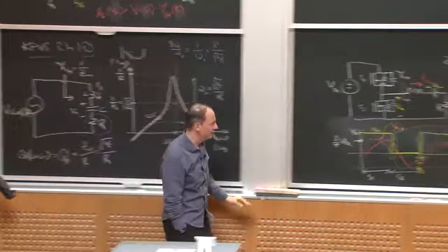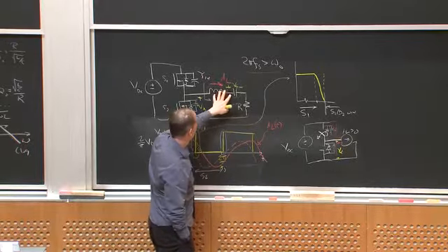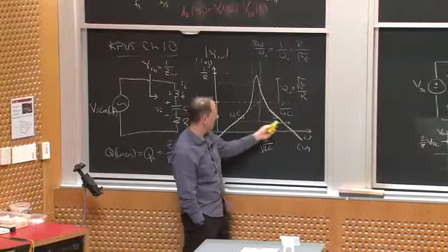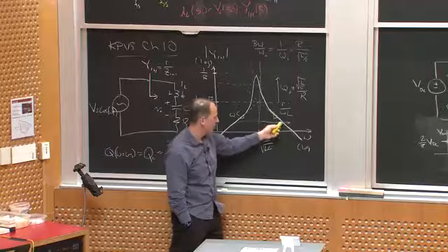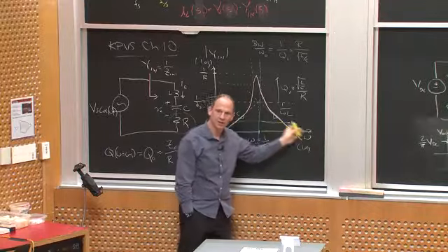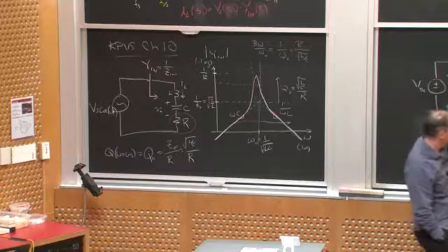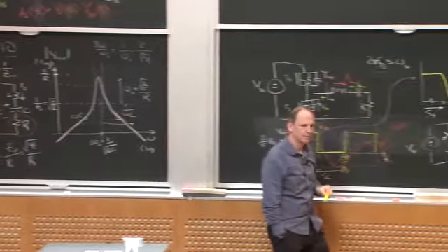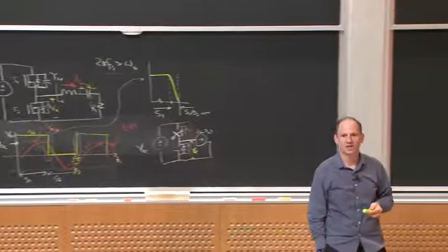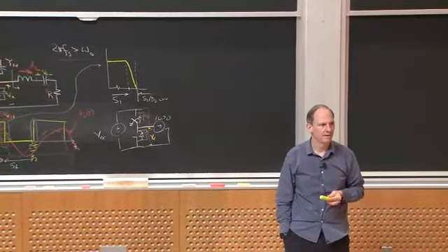On the other hand, if I make R too big, suddenly the quality factor of the network gets too low and I get this sort of frequency attenuation. I don't get good attenuation. I got to go to really high frequencies to attenuate things, right? So a challenge of these resonant networks is keeping the load resistance in an acceptable range for what you're trying to do. And that's sort of a trick of design. Okay. Any questions about that?